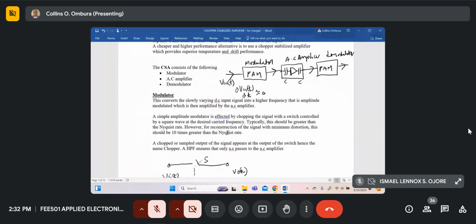For example, now I'm speaking to you through a microphone in the laptop. For you to hear high quality sound, you find it sampled maybe at 44 kilohertz. For a normal male voice, maybe the maximum frequency is only 6 kilohertz inside it. So if you're sampling it at 44 kilohertz, means 44 divided by 6 is how much? 6 times 8 is 48, approximately 8 times.